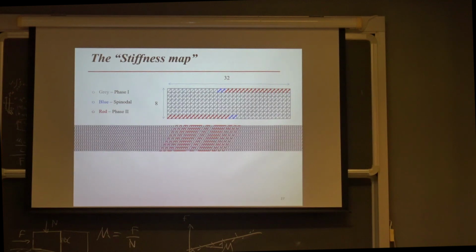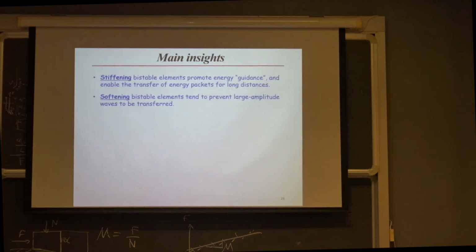If it were a linear spring with a control system that changes the stiffness of each spring every time, we would need a very complex control system. Instead, we can use multi-stable lattices that change their stiffness passively due to the bistable behavior. So like I said, the multi-stable lattice changes its stiffness passively to keep the energy from going deeper into the lattice. This is our explanation for the boomerang, a very interesting insight.